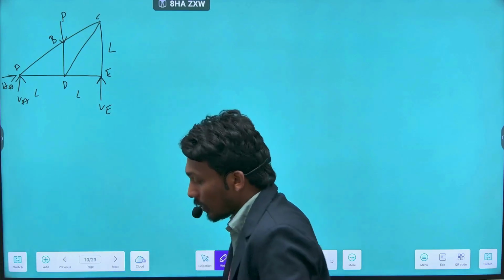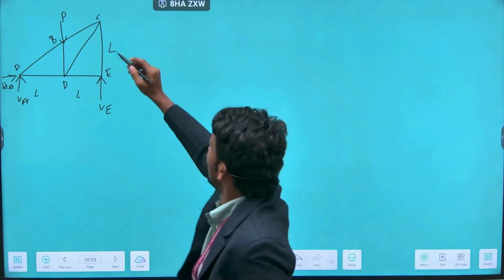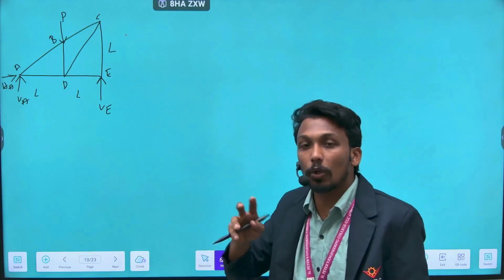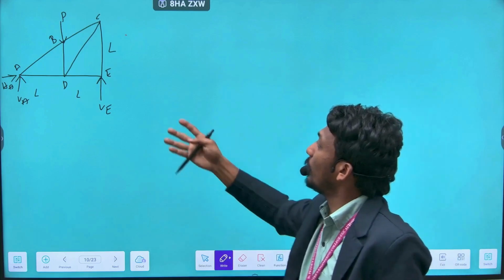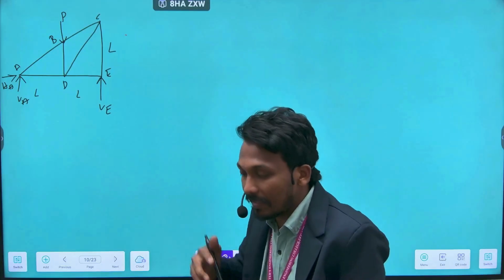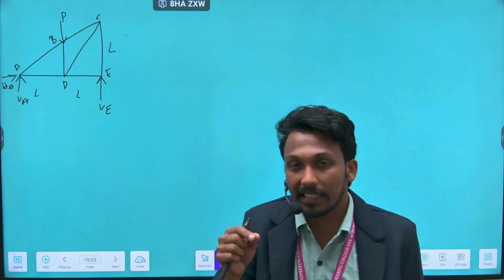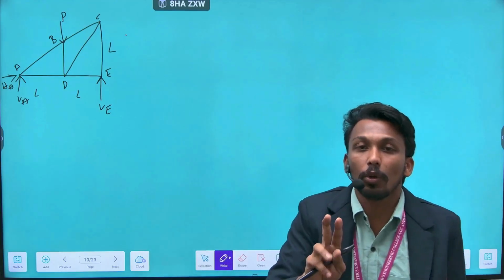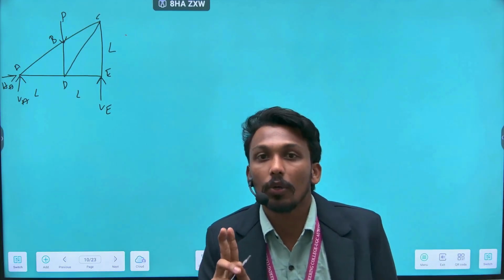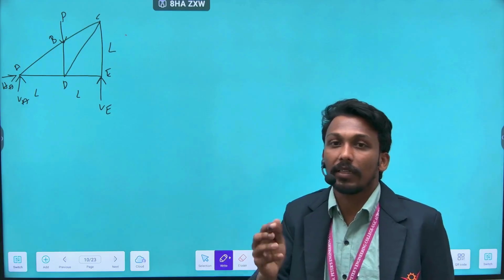In the method of joints, we have two equilibrium equations at a single joint. So if you have more than two unknowns at any joint, we will not be able to calculate the member forces there. So in this analysis, we select a joint in such a way that only two unknown forces are present, and then we proceed by applying the equilibrium equations.